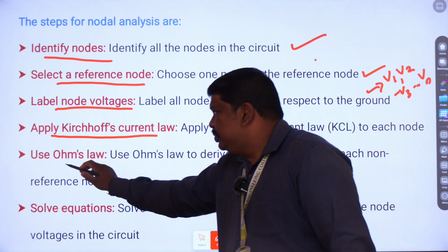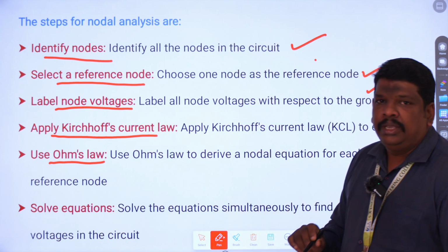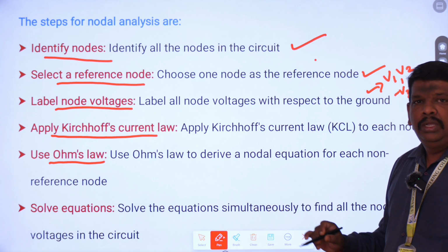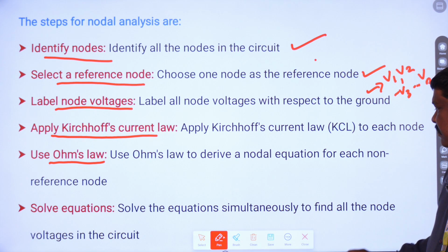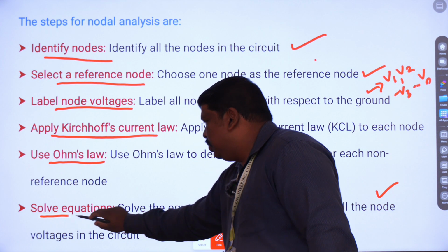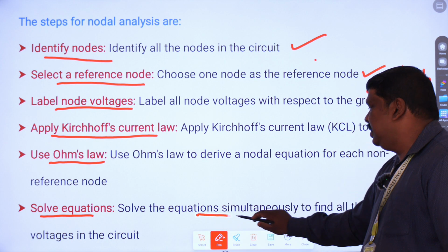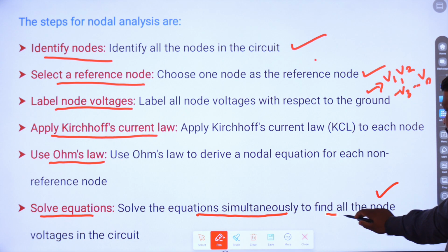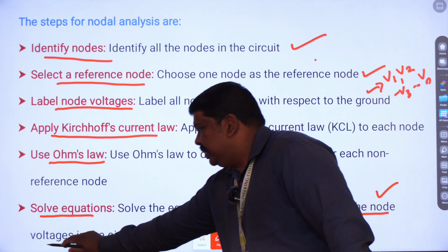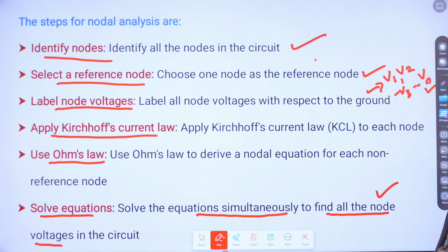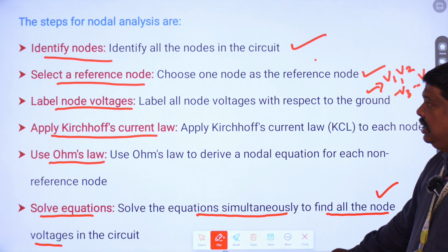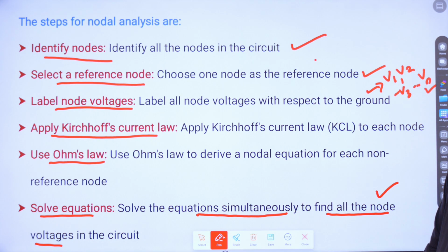After that, we are going to use Ohm's law relations in the same equations to find the voltage distributions among your nodes. Finally, we have to solve the equations simultaneously to find all the node voltages up to n. These are the steps involved in your nodal analysis.